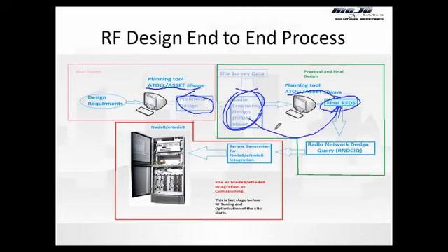But if that's not the case, and our design objectives were not met, then we'll put the data again in Atoll, replan it and run some iterations. When it meets our design objectives, we'll say all the coverage, throughput and quality design objectives are met, and based on that we will prepare our final RFDS.